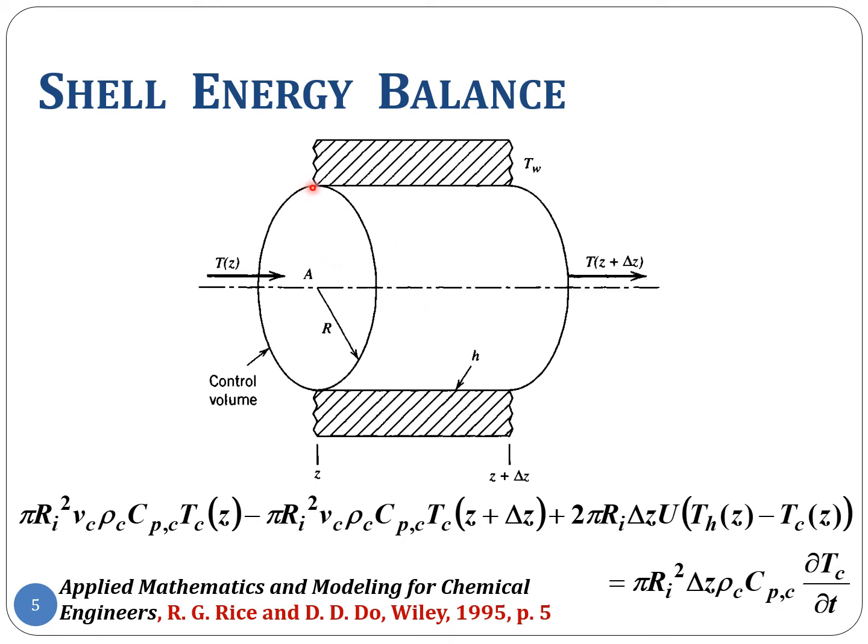So the radial temperature gradient measured at that boundary times the thermal conductivity, with of course the minus sign, that should be the heat flux. That is the rate at which heat is picked up by the fluid in contact with the solid boundary, right? And so one should actually write this as a condition that this heat flux is valid at the boundary r equal to capital R.